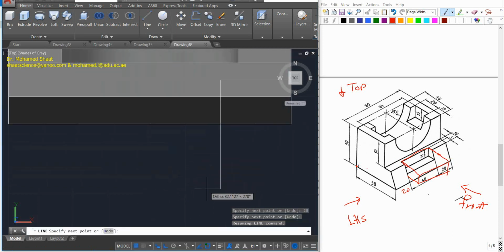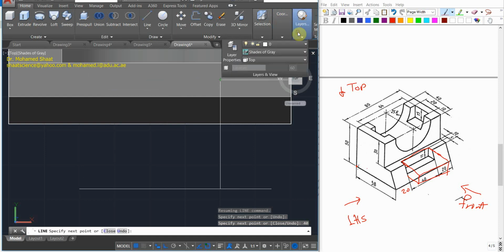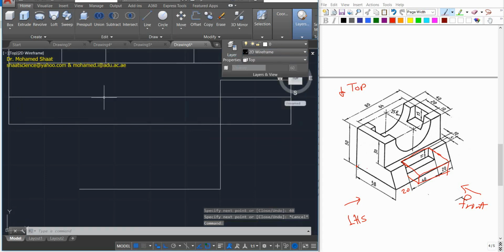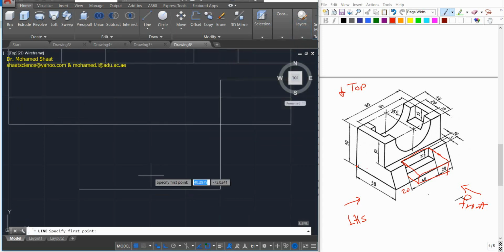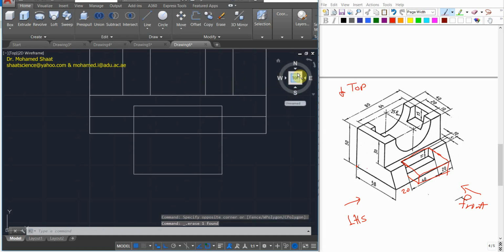Then I'm just gonna draw in a line, making sure that it completely covers the shape. Then you're gonna go to the left with 40, right? Just gonna go to the left with 40. Then I'm gonna go inside up to that point of intersection. If you can see the dashed green line, I can convert here to the 2-dimensional sketching, and this extension this way. Then you're gonna close the shape. Okay, then you can remove this line, because it is not part of the drawing.